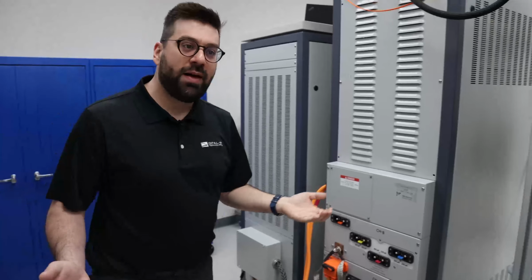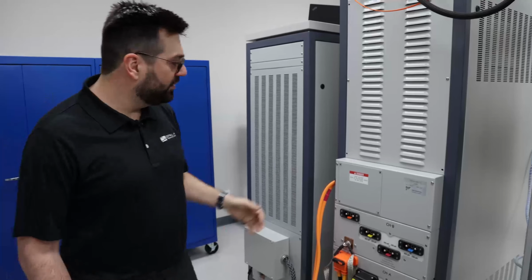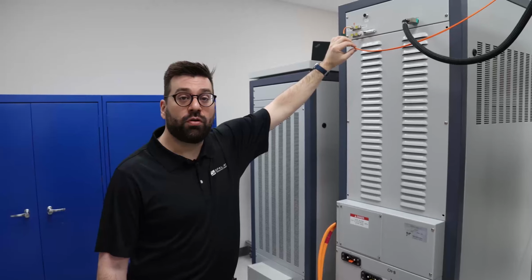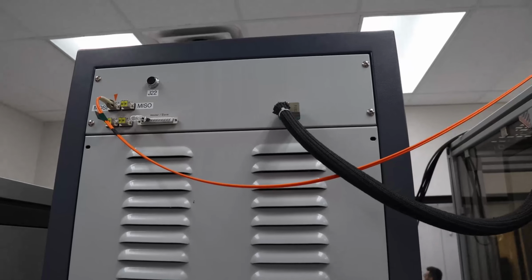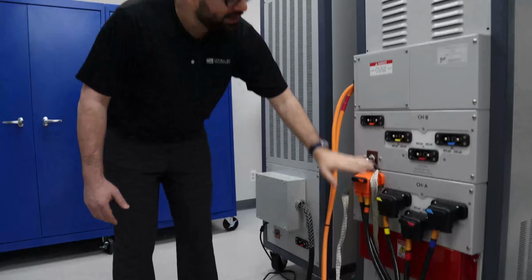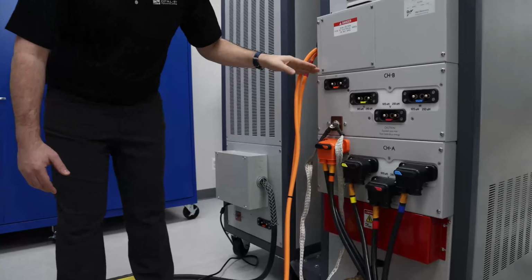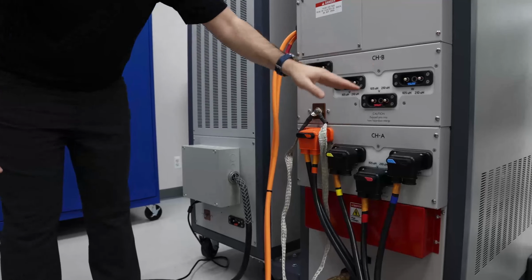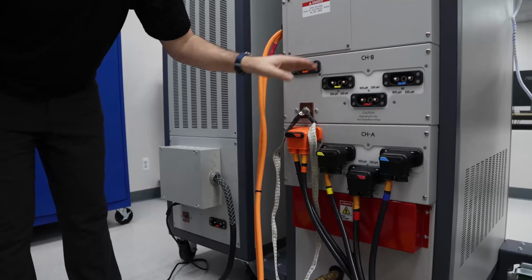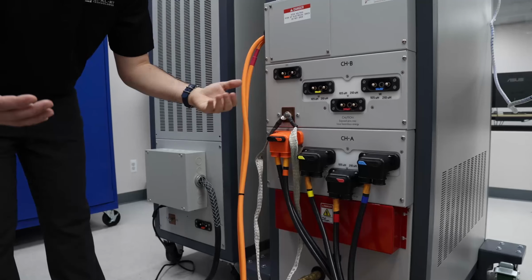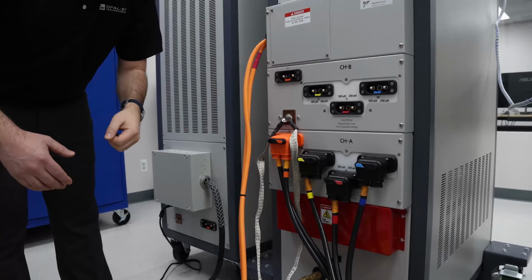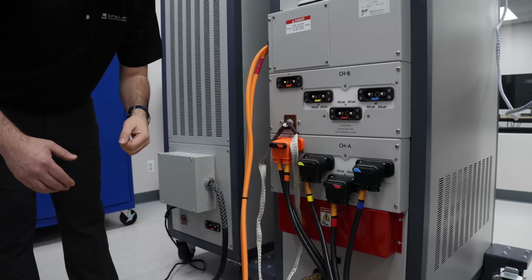So we're now in the back of the EME cabinet of DNV. First of all, here at the back, we have the SFP connection that we will use for the OPAL-RT real-time systems connection. And here you have the 2 channels, channel A and channel B. So you have your DC connection and you have the 3-phase connection to the inverters. As you may see, there are 2 channels, so 6-phase in total. It's up to the customers to use it as 2 independent systems or a 6-phase machine, as well as interconnections.